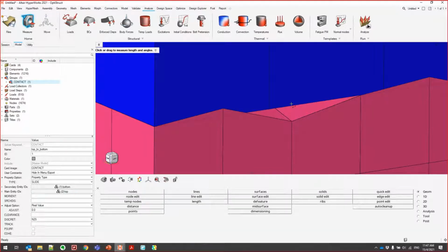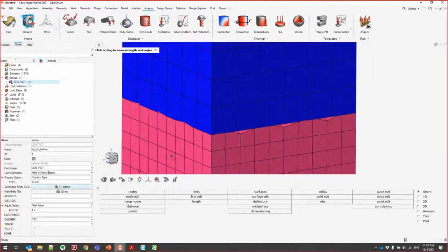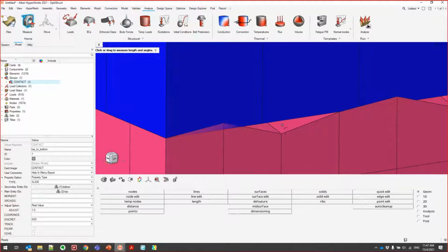If you want to fix the gap as well, you might want to estimate this gap here. Okay, so let's just put this as, the entire size is 1.67, so probably won't be that much. So I just put adjust 1 here. Okay, so this will fix both gap and penetration. Okay. Yep. So only node to surface will get to see this movement here. All right.